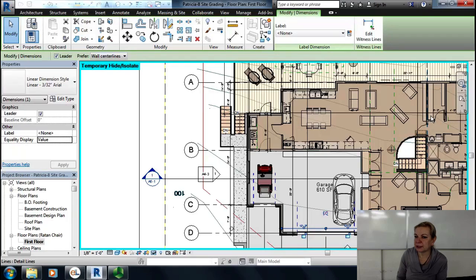Just making sure that you have your clearances for your bathroom tubs and your showers per required dimensions. If you do that, then your drawing should have, under general notes somewhere, that all typical partitions are 4-inch studs with 1/2 inch or 3/8 drywall on both sides, painted. So if you have a general note like that, then you're fine unless otherwise noted.